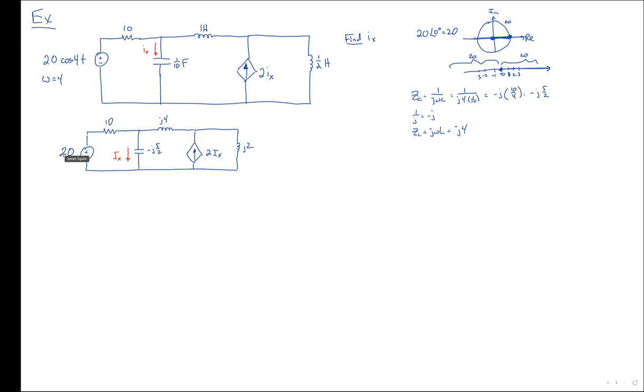Are there any impedances that directly simplify without doing source transforms? Are there any impedances that are in series or parallel? Lydia? No. So the best you could do is source transforms. But if you source transformed, although your 10 would be in parallel then with this guy, you couldn't simplify it because in doing so, you destroy your I sub x. So this is one where you really need to bite the bullet and just use nodal analysis, just the way it is.